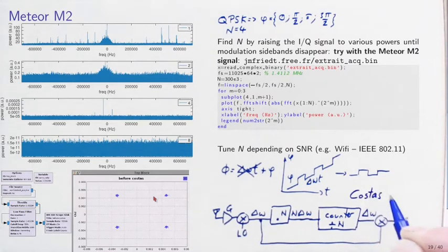The QPSK loop is the signal processing block for recovering the phase and cancelling the carrier offset between the received signal and the local oscillator by taking the nth power and dividing the output frequency by n, so that we are left with delta omega. Mixing the return signal with delta omega cancels this frequency offset and leaves us only with a random phase term.